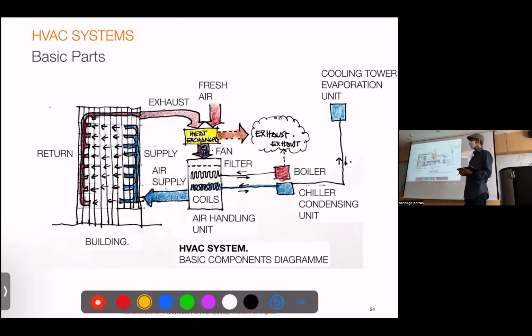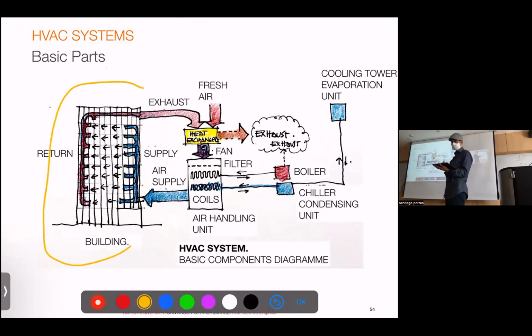And this is a very ugly diagram, but it's still my diagram to say what a full system for HVAC is, cooling or heating, right? So you have the building, which we are conditioning. And for each floor or unit, we have an impulsion and return of air, right? In this case, it is cool air because now it is getting warmer, and it goes through, it becomes warmer, and it's collected in what we call exhaust.